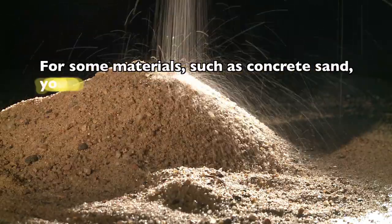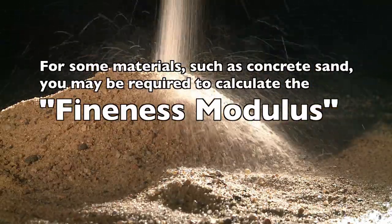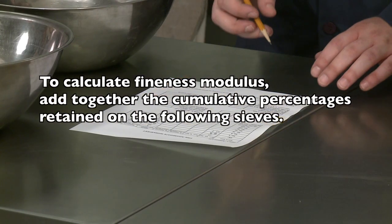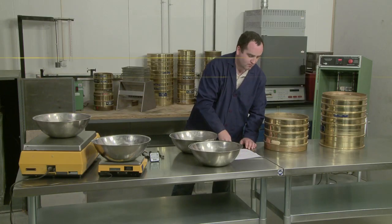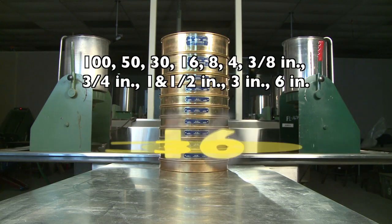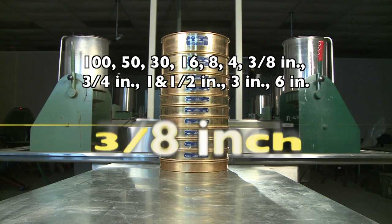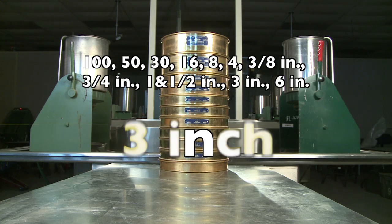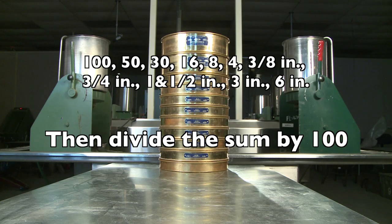For some materials, such as concrete sand, you may be required to calculate the fineness modulus. To calculate fineness modulus, add together the cumulative percentages retained on the following sieves: the number 100, 50, 30, 16, 8, 4, 3/8 inch, 3/4 inch, 1.5 inch, 3 inch, and 6 inch. Then divide the sum by 100.